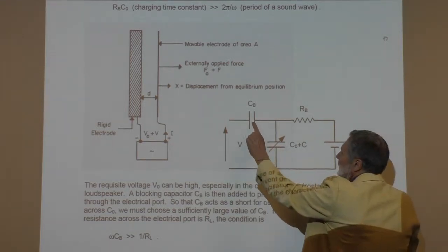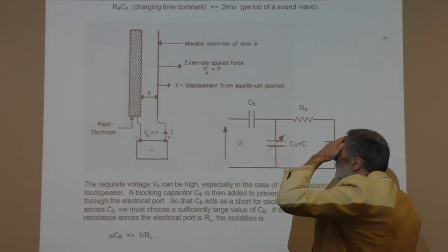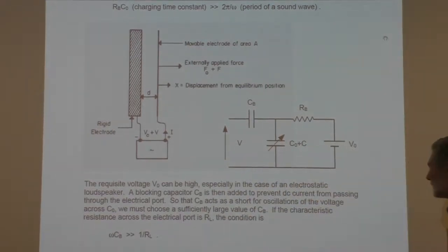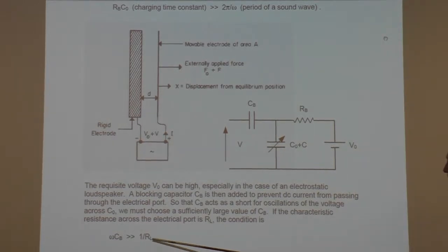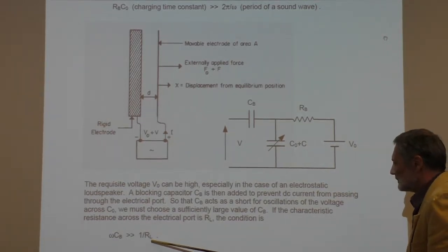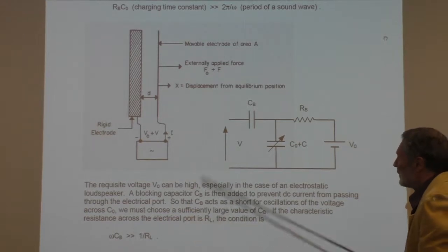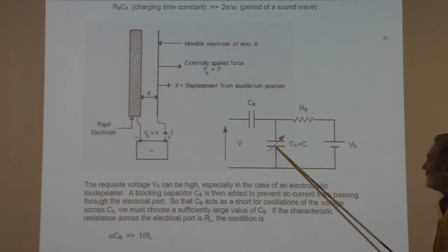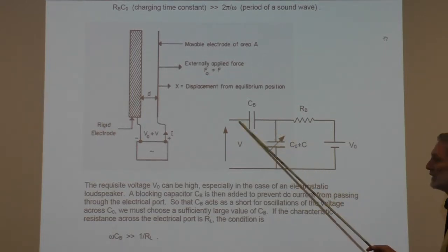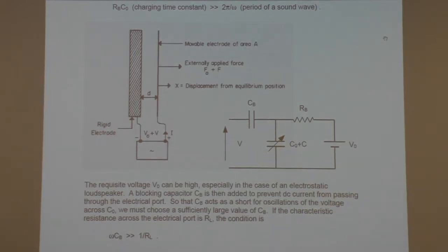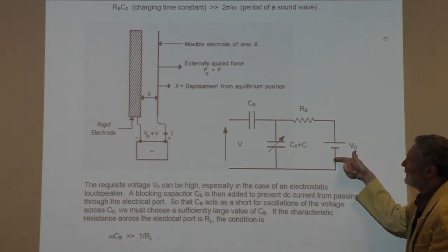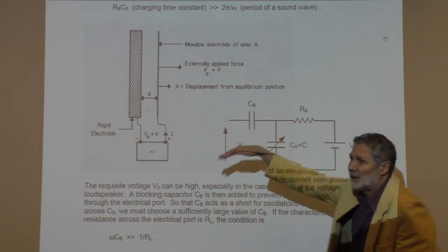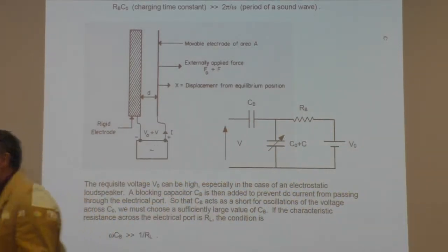We want this impedance to be much less than whatever impedance you have here. So I put that in terms of the load resistance. I guess this is just roughly right. There's some typical resistance here. You want this impedance to be small compared to that at the frequency that you're detecting the wave. Then this will act as a short. But because this is DC, at zero frequency, it's going to block any harmful current that can come in.